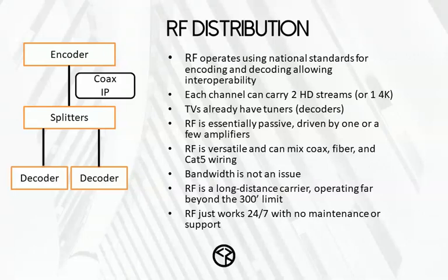So the way the channels are assembled, the frequencies they're at, the encoding that I use, whether it's MPEG-2 or H.264 is standard, and the cable system called QAM that we use to modulate and insert that stream onto a channel is standard, and the TVs know how to decode the stream when it gets there. So these days, most newer TVs can also decode H.264 as well as MPEG-2. So there's a little more variety in channels that you can send. And each typical channel carries 2 HD streams.